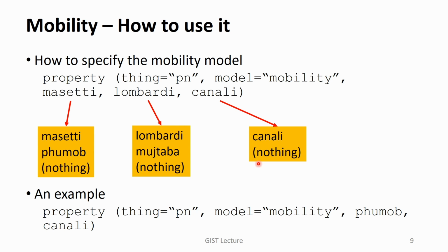For each item, you have available options, and it is noted that you may leave it empty. Without specifying a certain model, that effect will not be considered in your calculation. For example, this statement takes into account the doping and lateral field dependence. However, the vertical field dependence is neglected.